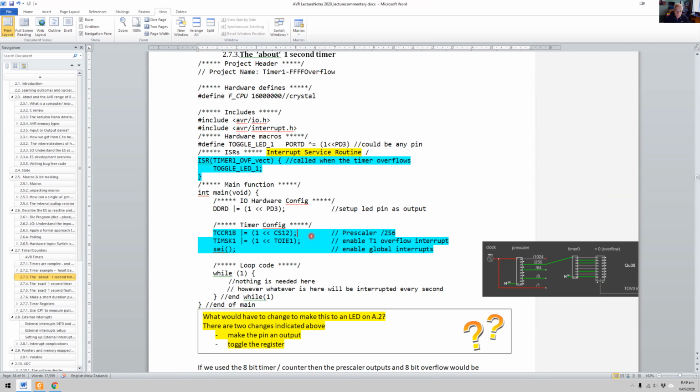The manufacturer says to us that when the device is powered up, all of the sequential logic in the microcontroller is reset. You'll notice Kevin talked about reset circuits in the first part of the course. So all of your microcontroller is reset and all your registers are cleared to 0. This is really important to know. If we're going to stick a piece of code in this part of our software, which means it's called once before we go into the automaton type while loop, then we can just configure this without worrying about bit 1 and bit 0.